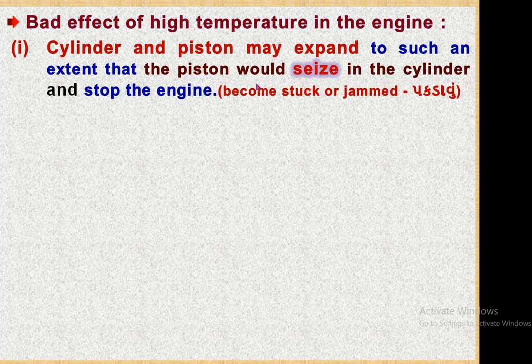First, the cylinder and piston may expand to such an extent that the piston would seize in the cylinder and stop the engine. As we know, as and when metal gets heated, its temperature rises, and due to the rise of temperature, the metal expands. So if the piston gets heated due to the high temperature created by the burning of fuel in the power stroke, it may expand.